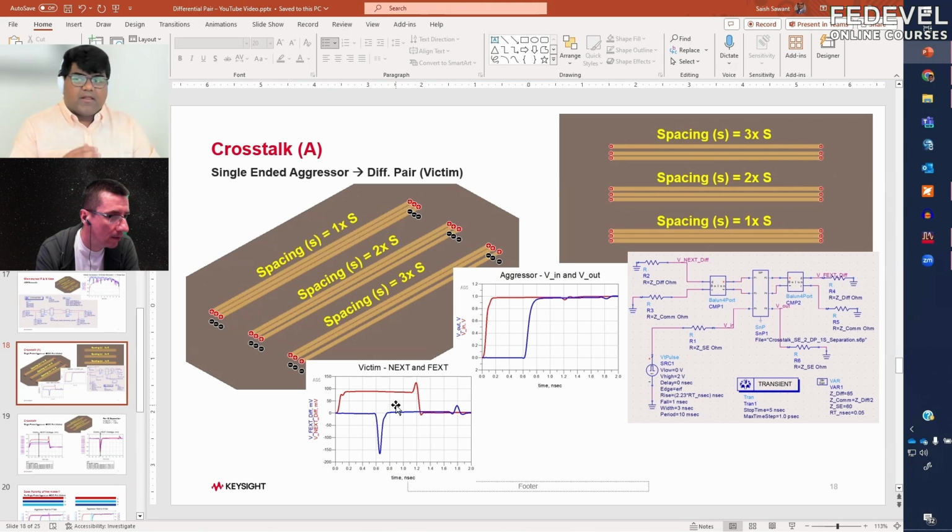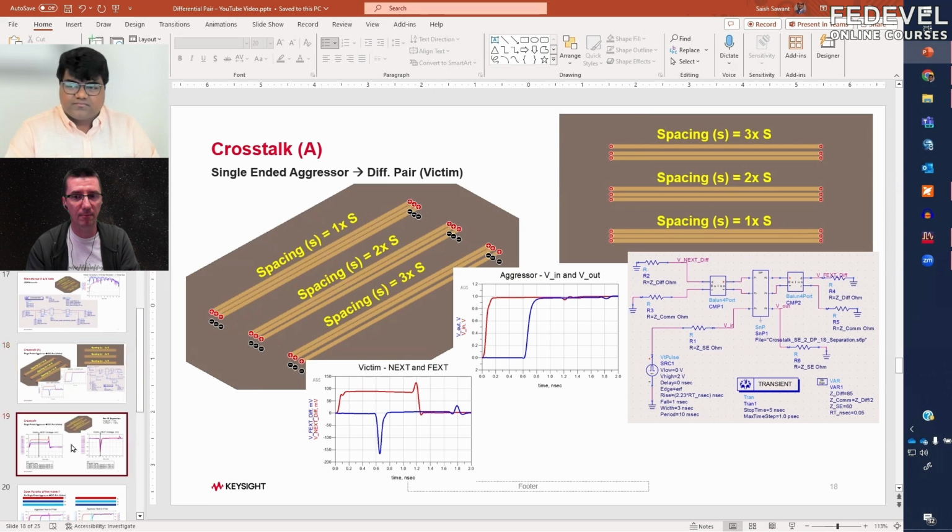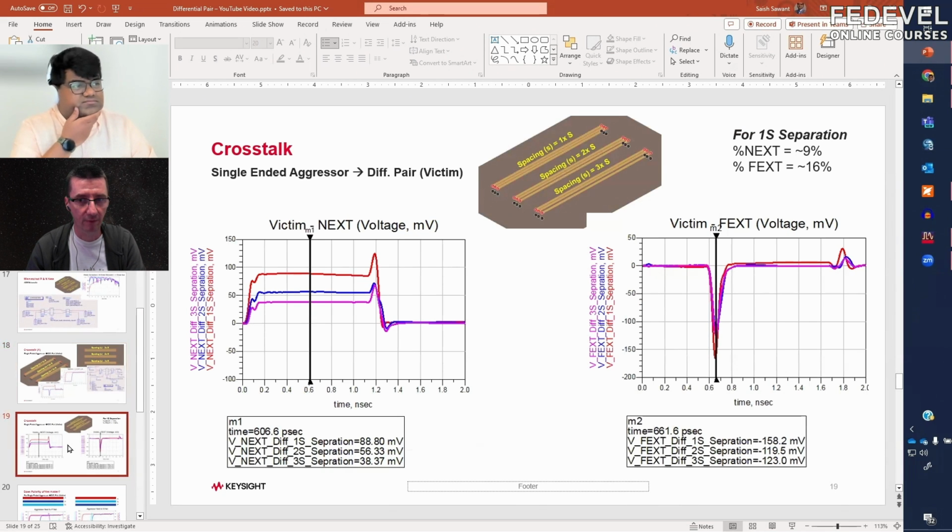And in this schematic we have used three spacings. For a differential pair we have a width and then a spacing. If we retain that same spacing S, then we have three signal tracks next to each other. I'm curious, because this is very important: when someone is doing PCB layout, they would like to know how far from the differential pair they need to route. So let's have a look.